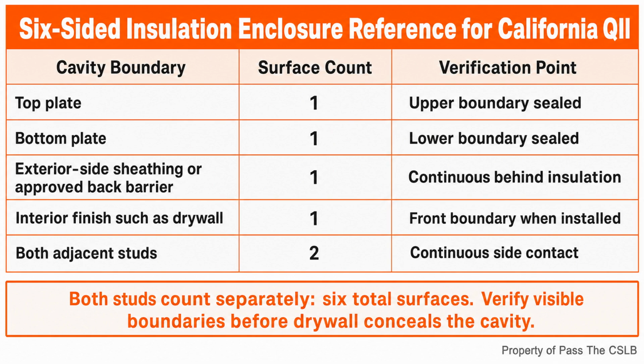The corrective work is not to pack more porous insulation into the opening. The field issue is the missing rigid boundary and its unsealed penetrations. Catching that before the surrounding finishes arrive keeps a barrier detail from becoming demolition and rework.